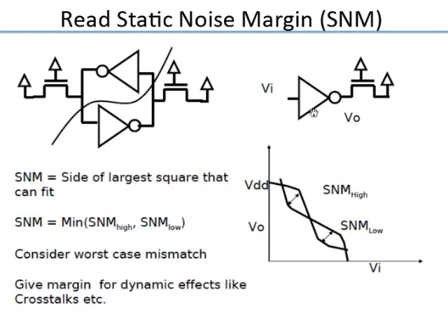Okay, now you look at the VI versus VO DC transfer curve. So you plot VI and then you have VO. So when VI is 0, VO is 1. There's nothing magic there. But as Vi starts increasing, you have output falling. And remember, for an inverter, the output fell all the way to ground. Right? If you recall the DC transfer curve for the inverter. Whereas here, the output doesn't go all the way to ground, it gets stuck here.